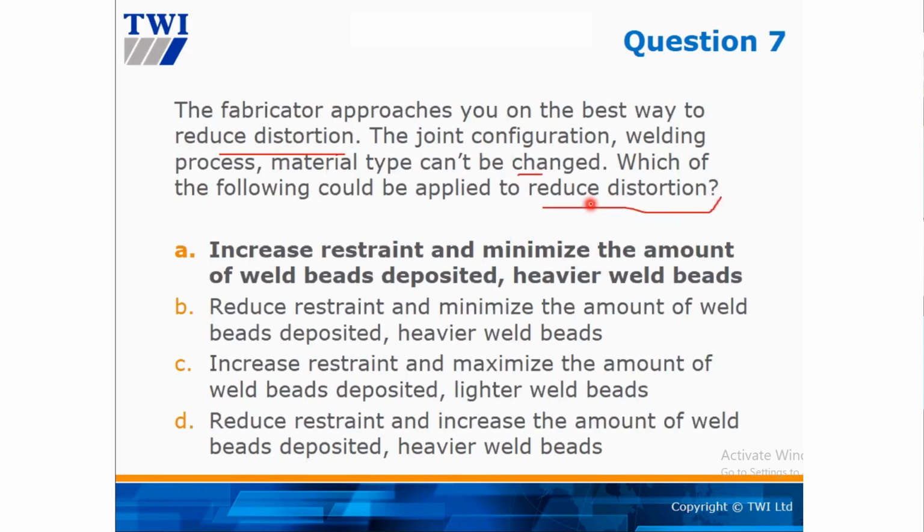All right, reduce distortion by increasing restraint. That's correct. Material not free to move. Minimize amount of weld metal deposited and heavier weld bead. All right. We're going to discuss the amount of weld metal deposited, minimize, and heavier weld bead here.